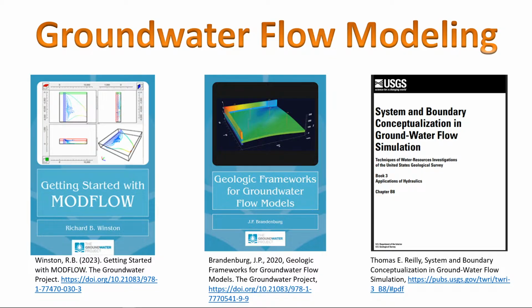So here, these are some good textbooks if you want to learn more about this. In this module, you will learn how to set up and calibrate a groundwater flow model. For this, we use a code called MODFLOW. MODFLOW is a computer code that solves your groundwater flow equation with all these different parameters like pumping, injection, boundary conditions, recharge. As you will see, MODFLOW has all these packages.